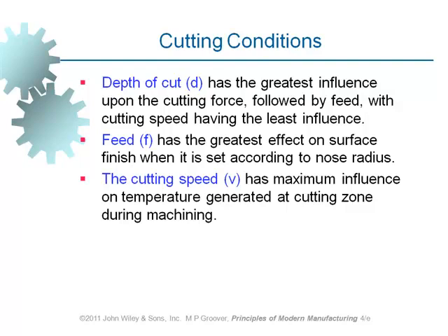In industry, people do it this way. They choose the highest feed, which can give us the result, the required surface finish. We know that it's the feed rate which decides the surface finish, the most important parameter, I mean. So choose a feed rate which is maximum and is still giving you desired surface finish. Does that make sense? So we've got maximum productivity, still we've got desired surface finish.